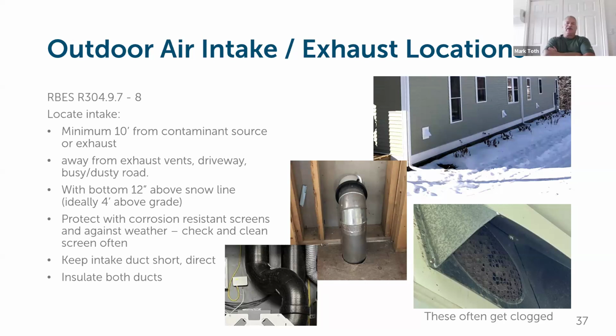We don't want them over the driveway, because if you're going to idle your car possibly in the winter to warm up a little bit, we don't want the exhaust coming in. You don't want it near your barbecue grill outside because you don't want to pull that smell into the house. So it can get a little bit difficult to find a clean area to bring fresh air in from, but that's extremely important. And also the snow line is extremely important. We have another picture later of an example where that wasn't done.